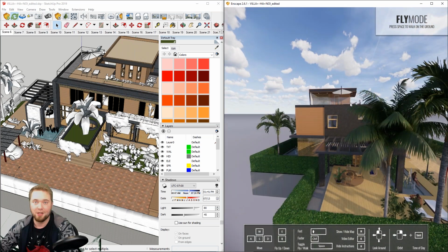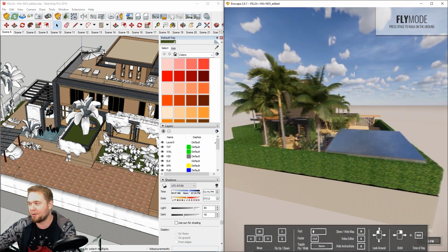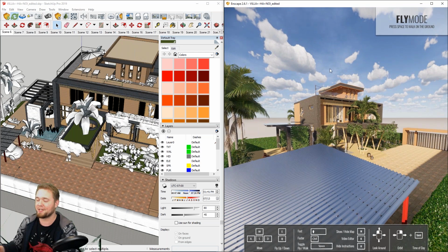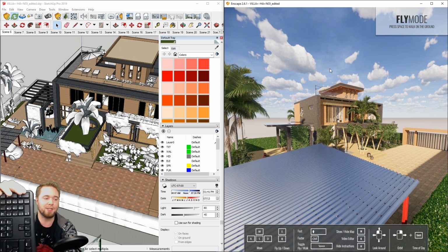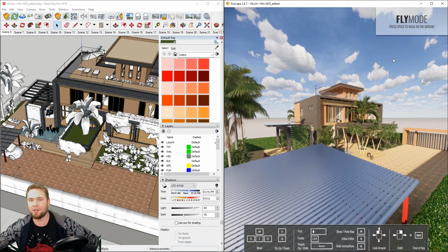We also have a knowledge base article on movement in Enscape, and we'll be sharing that with you in a second. But in this article, you also see some more advanced ways of movement, like the numpad on your keyboard, which you see here. That's this block of numbers on the right side. And if you use that, you can imagine it like a sort of view cube that you might know from other software.